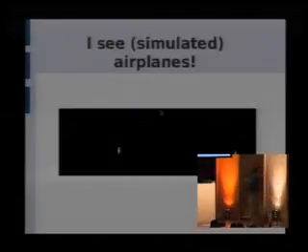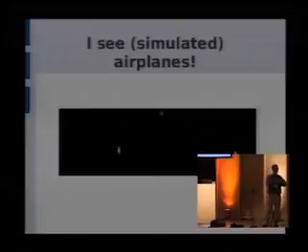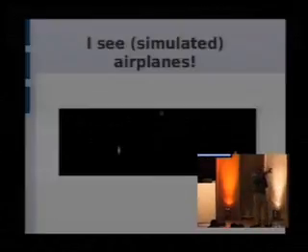But if they're really cranking it up, you have this idea that how you figure out where, you're trying to make this time measurement, what you're actually doing is correlating. You're sliding a delayed version of the signal against a non-delayed version of the signal, and it's brute force. You say, okay, try matching them up here, and you basically compute this. It's the correlation, but basically you take the complex conjugate and sum them.